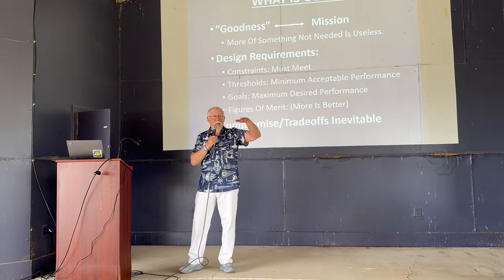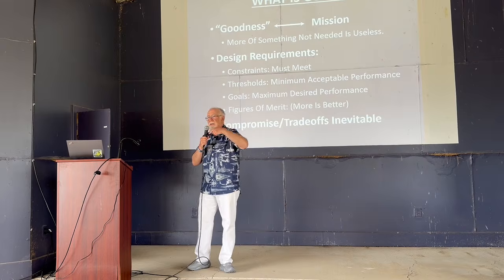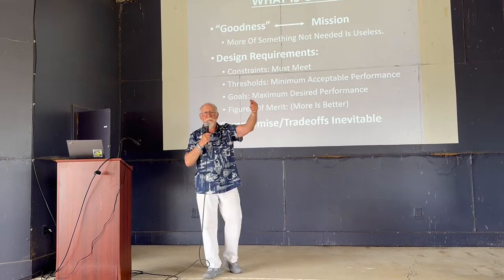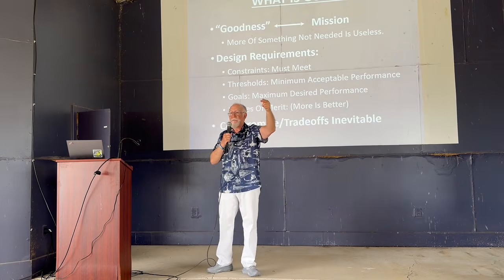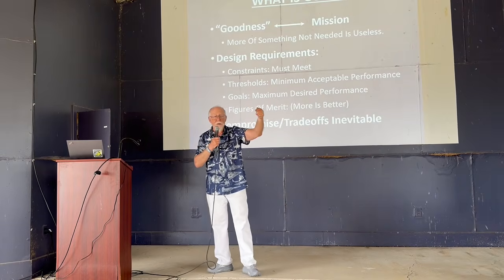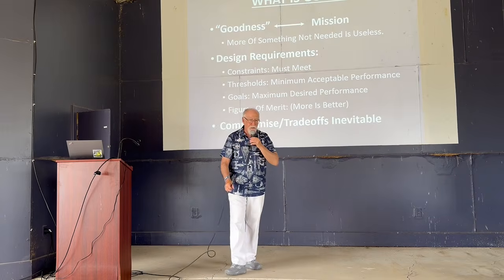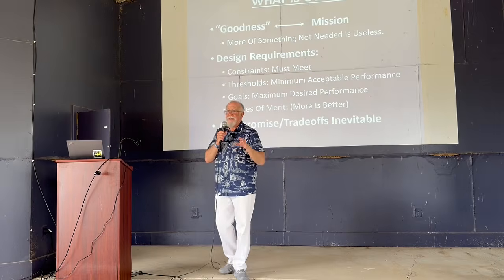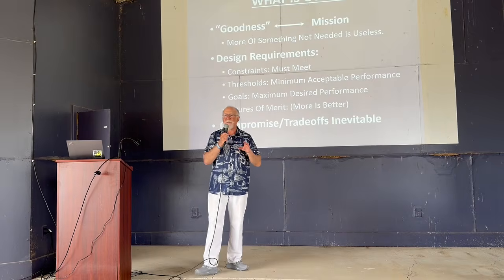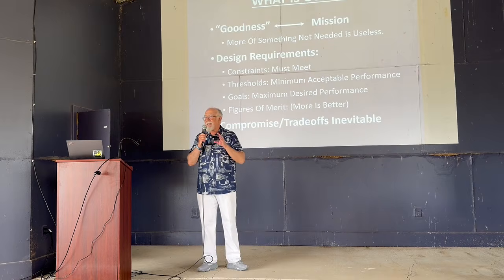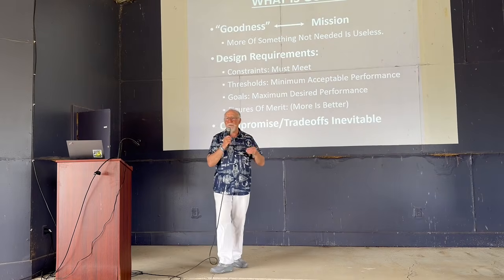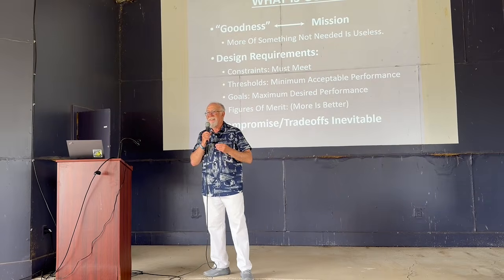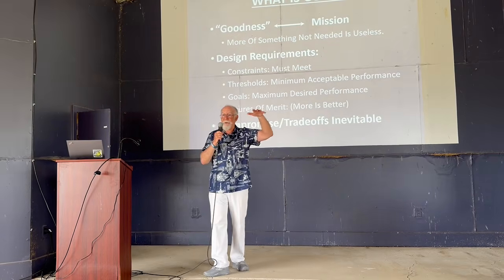And those are important to look at too, because what the customer is telling you is you don't get credit for more than that. And that in turn means that if you try to give them more than that, you're giving them something more expensive. I advise at several universities, and every year in senior design, there's one team that will proudly tell us how much more performance they give than the request for proposal. And it's kind of sad when I always tell them, well, guys, what you have just shown me is your airplane is more expensive than your competitors. So take a look at what that max goal performance is also.